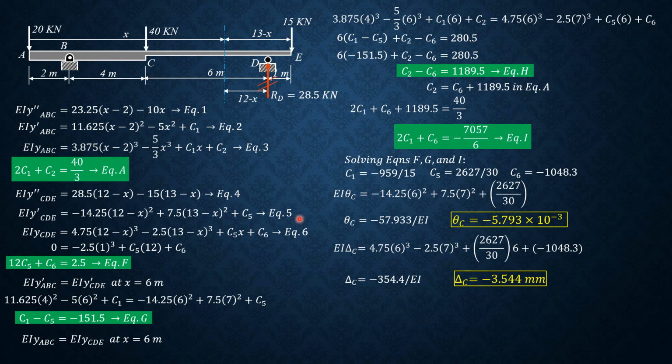So that's it for the other solution, so that you will experience this solution for the case when the left side has so many forces that it's complicated. So you use the right side, the forces to the right of the section, and counterclockwise is positive if you do that.